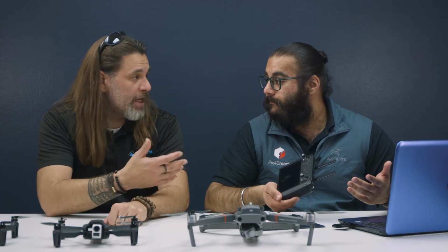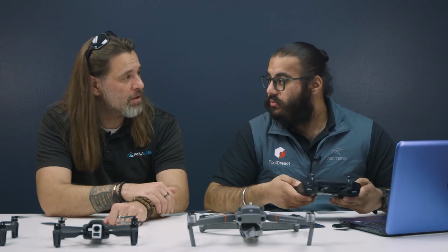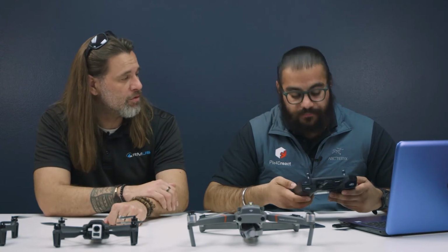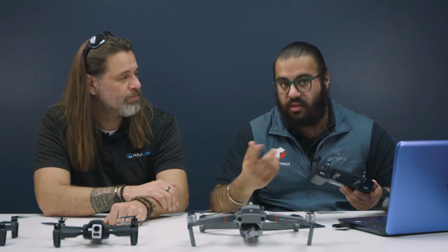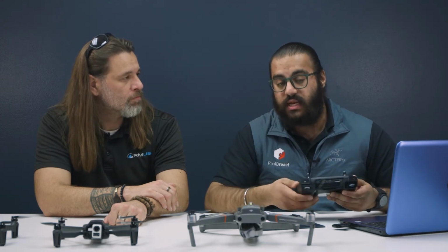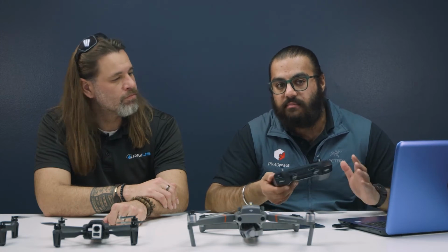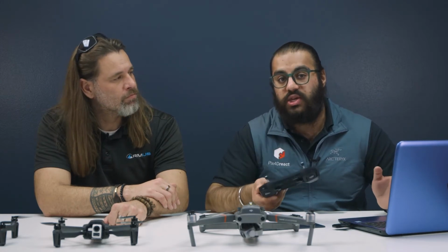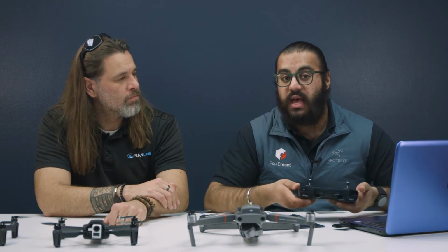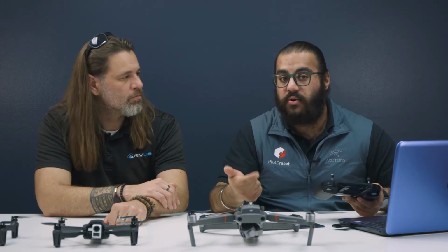So we did do our data capture today on the two different machines, and on both we basically used the Pilot app to do the mission. We used DJI Pilot, and you saw that in the video when we were outside flying, and the way the mission was set up. That's very simply to prove the point that it doesn't matter what application you're using to fly your grid missions, as long as the images have the right amount of overlap and they're clear and in focus.